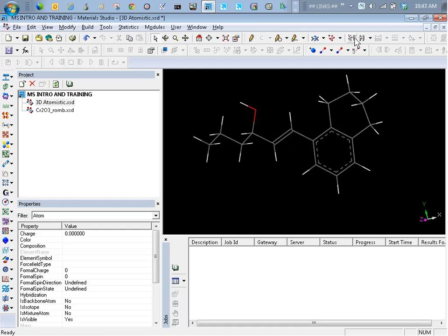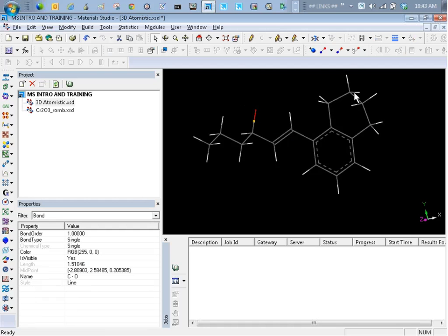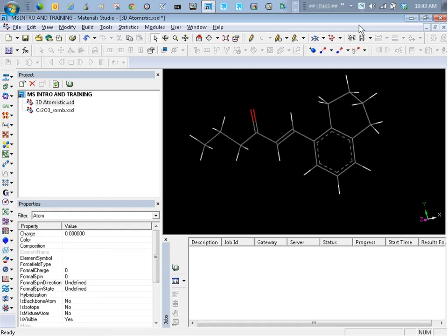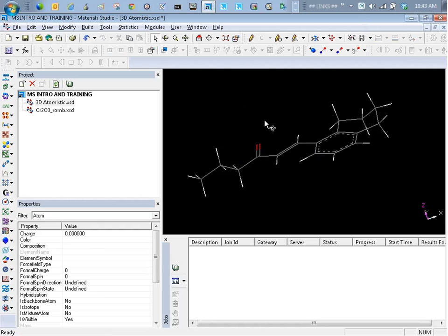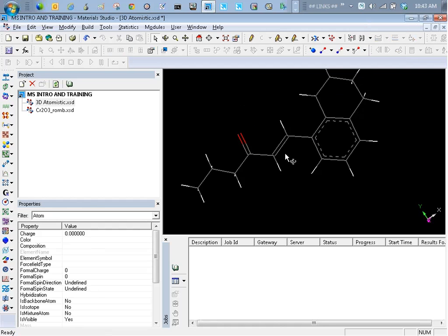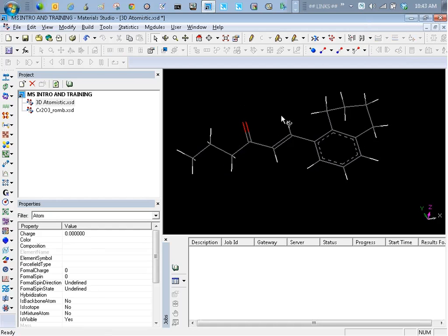And then if I use this, which is my simple bond length and topology cleaning mechanism, it changes that. Again, one can change bond orders as well in this. You can just delete that hydrogen. This is trivial stuff. I can select that bond and I can make it a double bond. And then say, now I can start to go in and delete and sort out my structure. The hydrogen fix sorts out my valency, and then I can do my cleaning, and you notice now that sp2 carbon becomes pseudoplanar. So now I'm starting to get a delocalized structure there, ketone, orthopolymerism, etc.